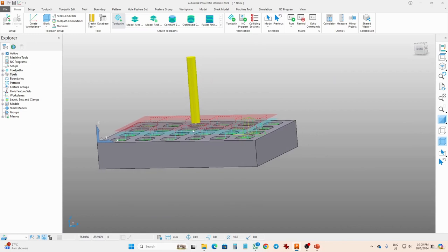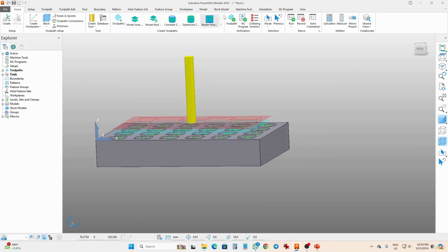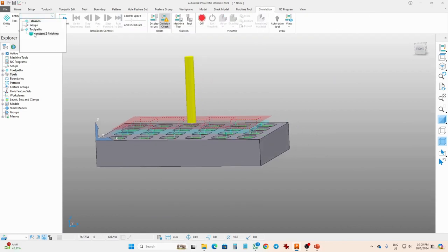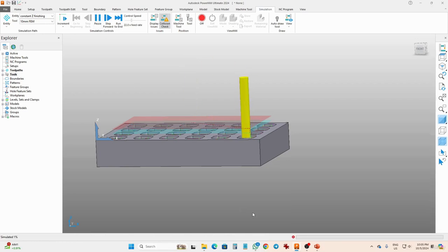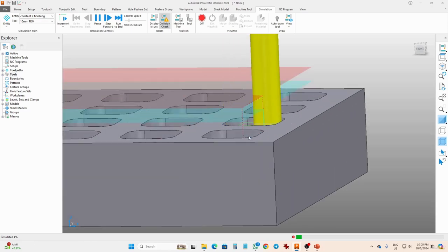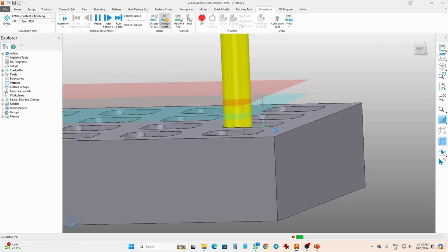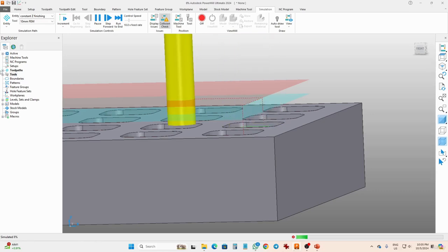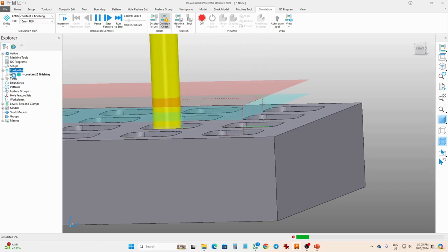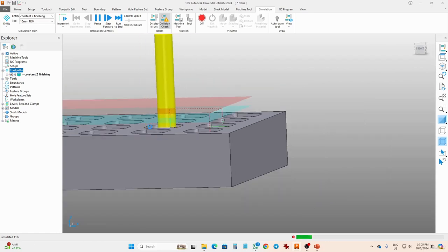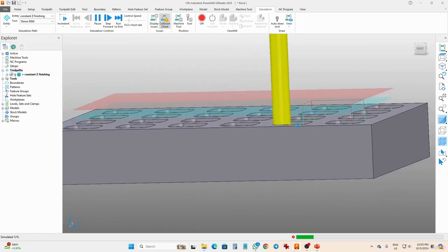Whenever you simulate that toolpath, no such collision will happen. You see that the tool removes the material and then moves in an upward direction without touching the workpiece. That's what we call a correct toolpath. It's safe. You see that the tick is being shown again. That's a good thing. By applying the simulation right now, you will find out there are no gouges.